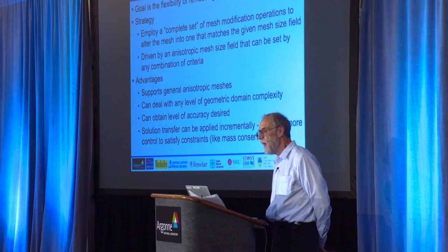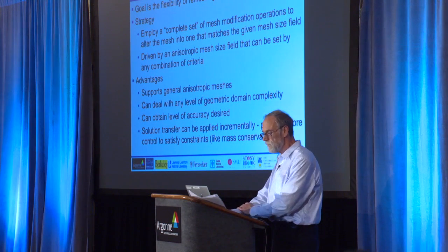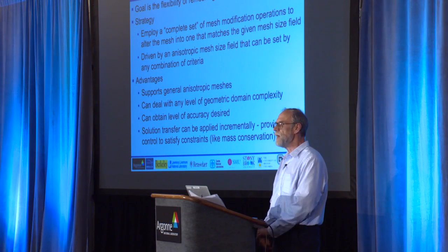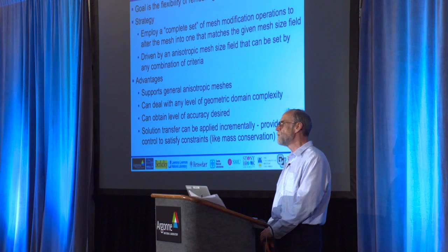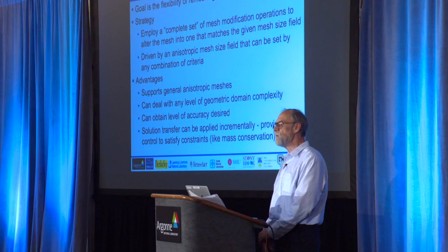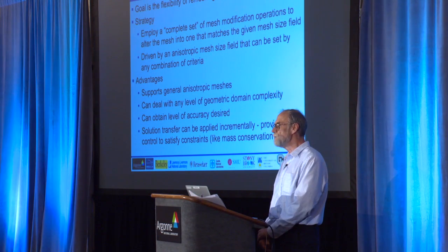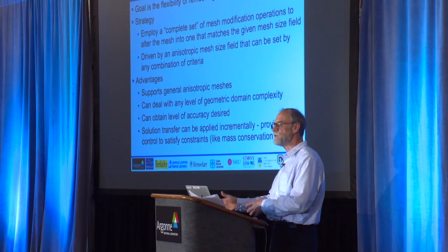And that's true, you do save mesh generation time, but a much more critical aspect is that if you're doing the mesh adaptation with these local operations, you can do the solution transfer locally as you go along, and that is much more efficient and more accurate. So when you go back to the solver step with this new mesh, you don't have some of the startup problems you often have if you have to do general mesh-to-mesh transfer.